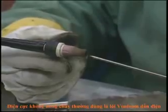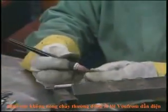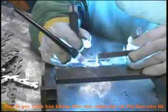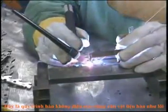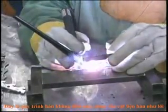The most common non-consumable electrode is a tungsten rod, which carries the electric current. If a welding operation using a non-consumable electrode also requires a filler metal, it is supplied by a separate wire, rod, or consumable insert.